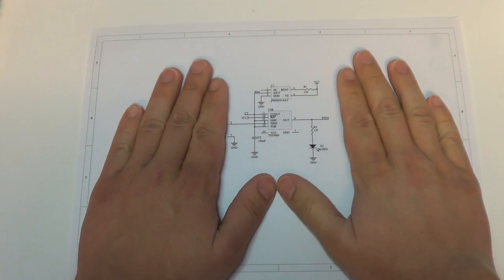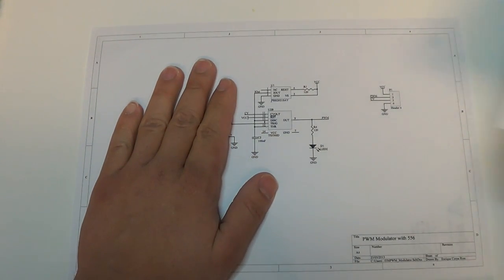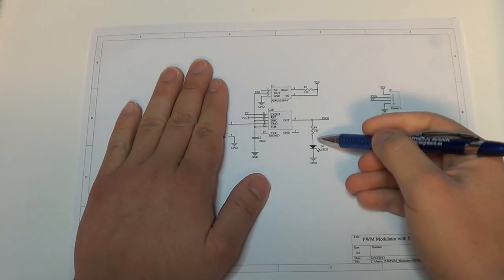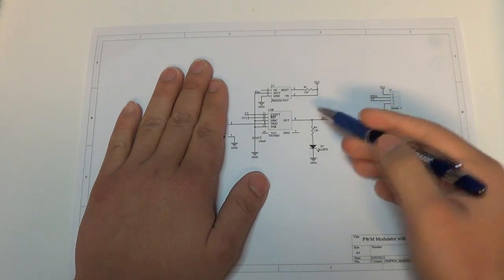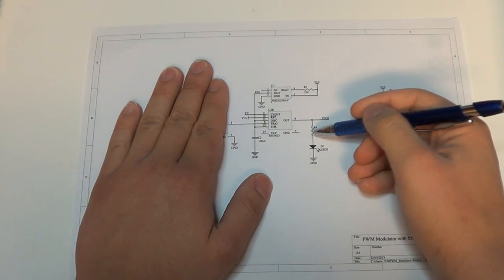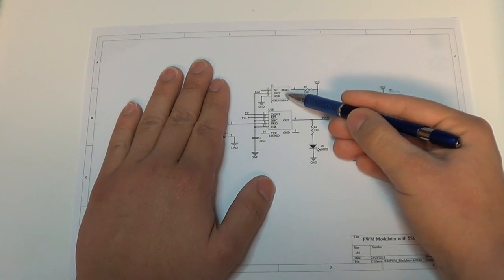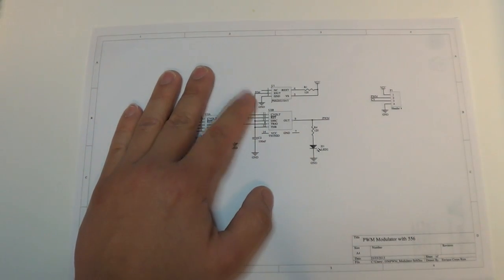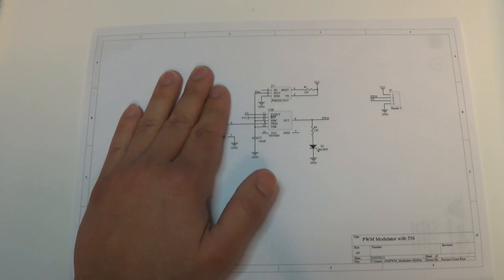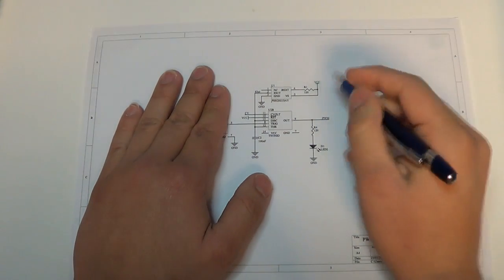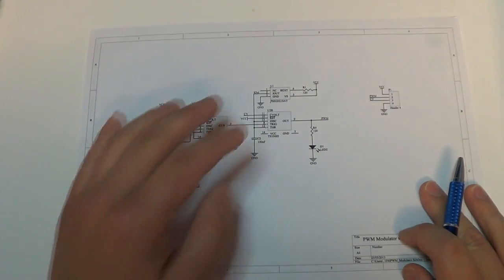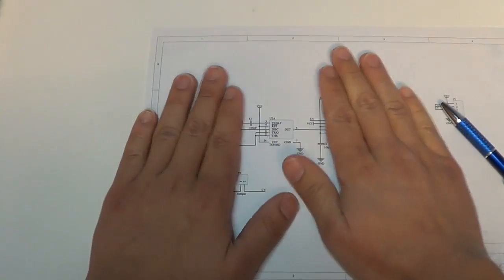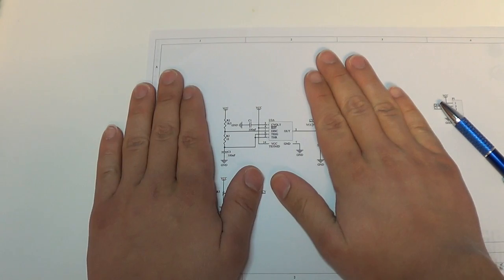And as you can see here, this is the datasheet circuit, and I am using a LED to see the output, to see the change in the brightness, and this integrated circuit over there is a current source, and you can select the current of that current source just with one resistor, and that's it pretty much. And as you can see, this other part of the circuit is my oscillator.